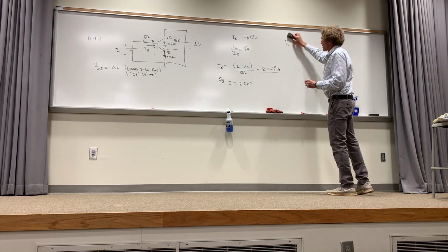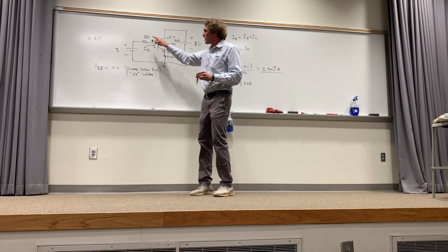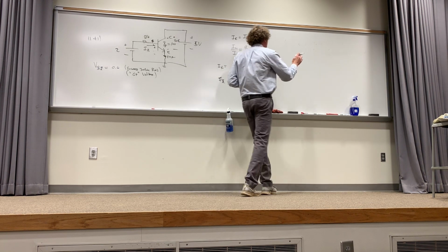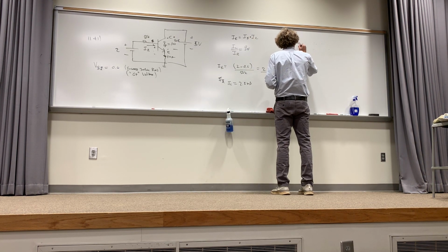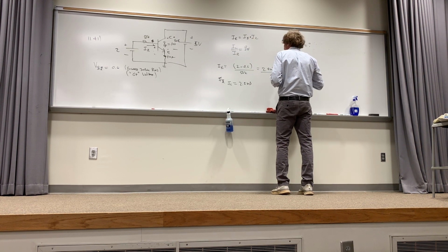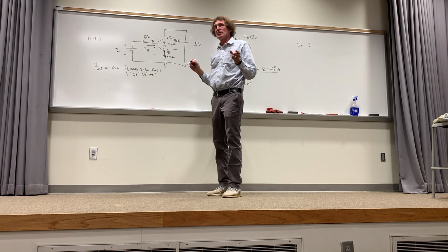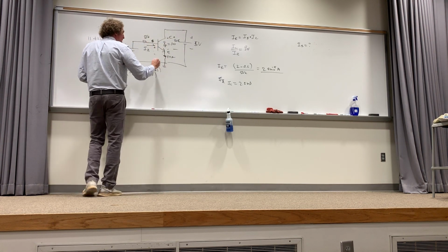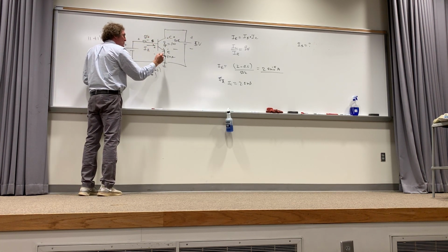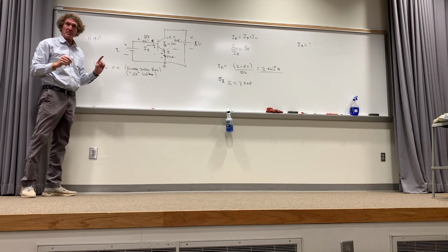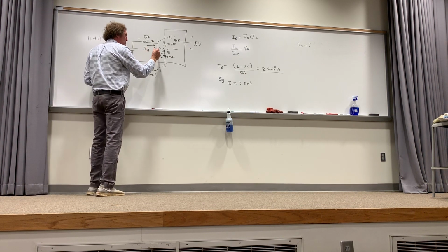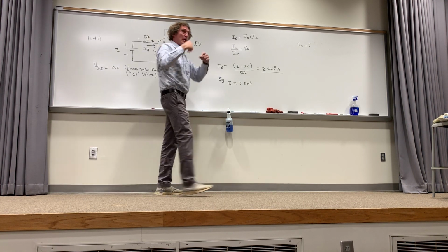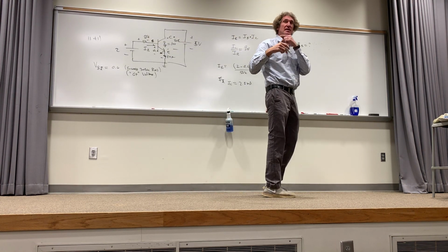Remember, the key is getting the current in the base of this circuit, correct, class? If I want that current, well, I've got 2 volts driving. I'm going to just put it down. I want IB. That's what I'm after. So here's what I'm going to do this time so you can see it. I'm going to go around this loop and take the voltage drops and set it equal to 0 so you can see it exactly. Are you with me, class? Remember, this is plus to minus. Right there, 0.6 volts. So I'm going to go around there this time, the first time. Then you'll see how to deal with it.